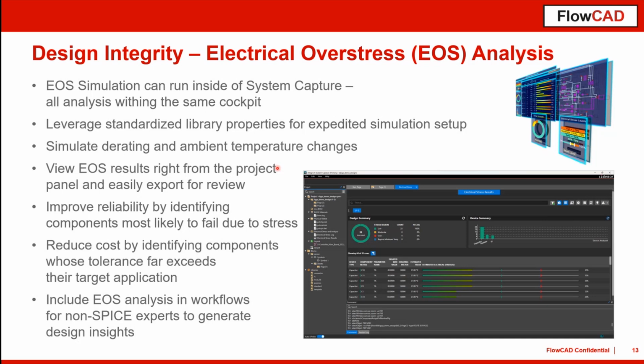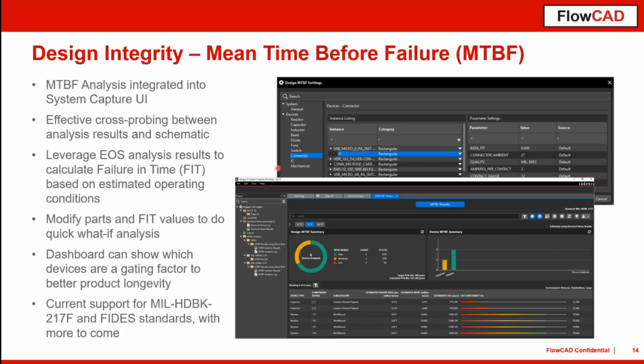And as I mentioned, System Capture is not just drawing a schematic, it offers way more possibilities. MTBF analysis is also built into System Capture. We currently have these two standards, this MIL standard and this FIDES standard. Some people told me that they are quite old and they might need additional standards. So if you need different things, we can for sure address this to Cadence, and then they will sooner or later build this into the tooling.